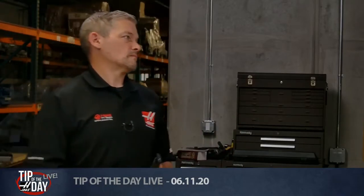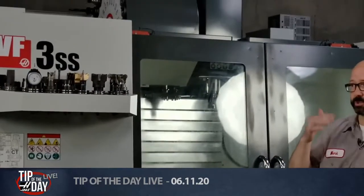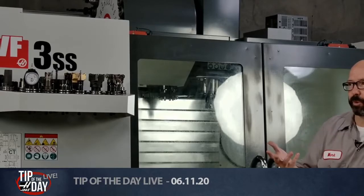Recently we had a question about what to use, if it's G43, G44 for tool touch-offs. And I said, really, G44 is the code if you want to crash your machine. There's no good reason to use it. I know we've all seen the t-shirts that say there's no place like G28, G0, Z0, right? Or there's no place like home. That code on all of those t-shirts, G28, G0, Z0, will crash your machine, right? So if you got that t-shirt and your machine is toolbox, you've got to add a G91.